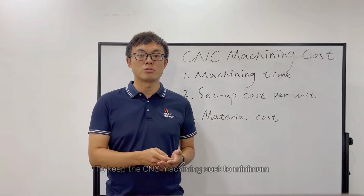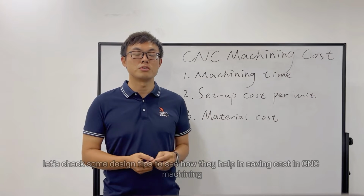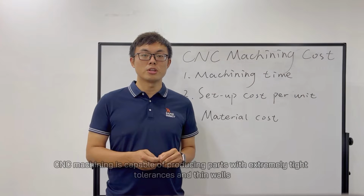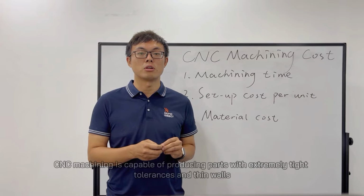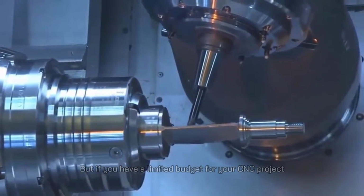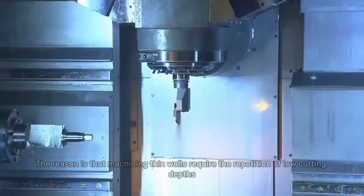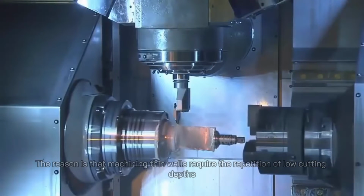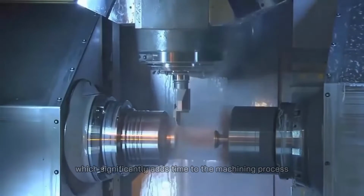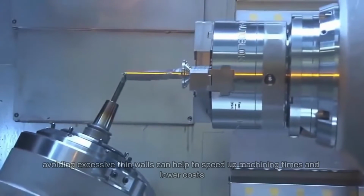To keep the CNC machining cost to a minimum, let's check some design tips to see how they help in saving costs in CNC machining. The first design tip is to avoid excessive thin walls. CNC machining is capable of producing parts with extremely tight tolerance and thin walls, which is about 1 mm. But if you have a limited budget for your CNC project, or your design doesn't necessarily require very thin walls, just avoid them. The reason is that machining thin walls requires the repetition of low cutting depth, which significantly adds time to the machining process. Therefore, avoiding excessive thin walls can help to speed up the machining time and lower costs.